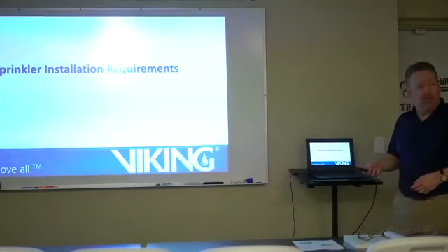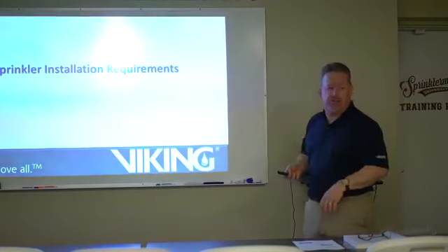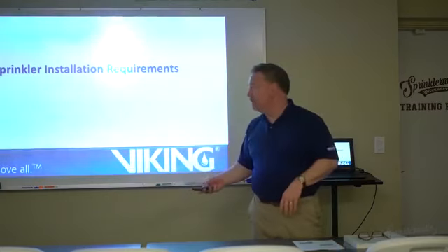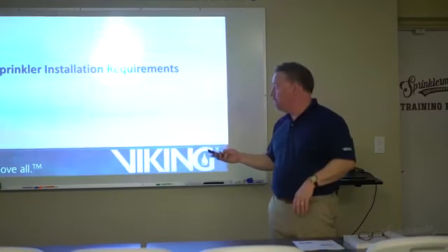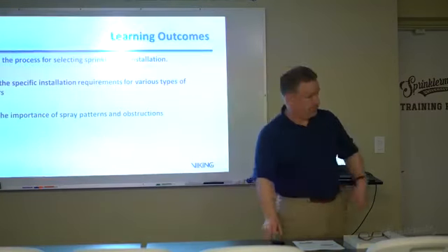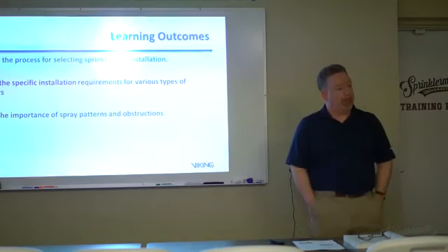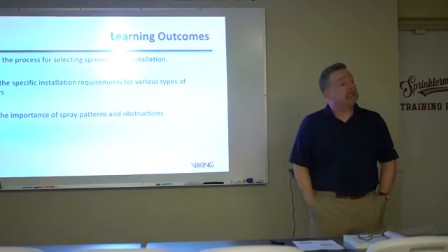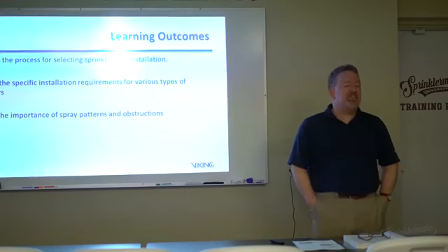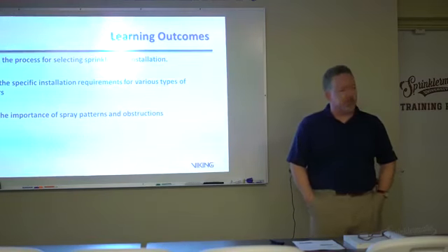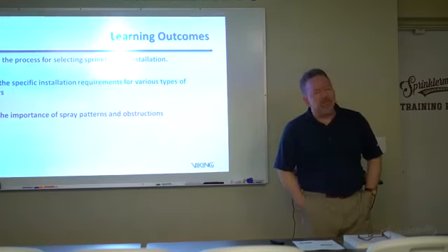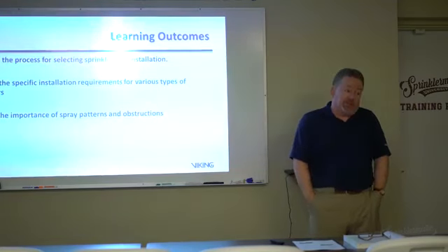Can I ask you a question? Sure, you may ask many questions if you'd like. If you design a building for a light hazard occupancy, obviously you're limited to four or five sprinkler heads that are available. Well, there's more than that. They just need to be quick response. Viking builds many quick response sprinklers. It's just that you have to use them.